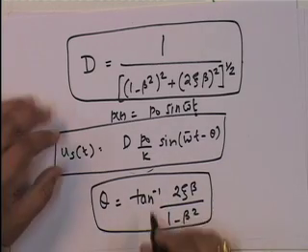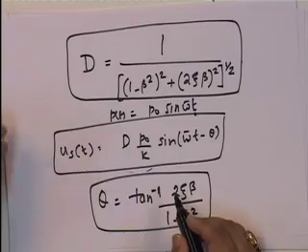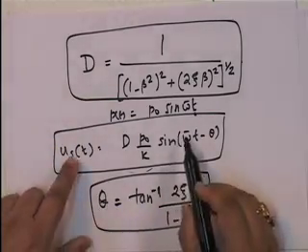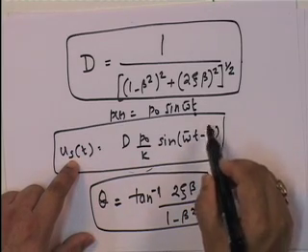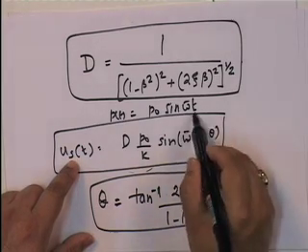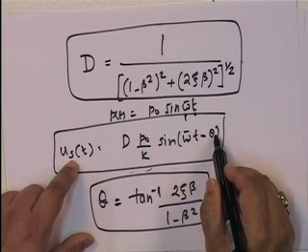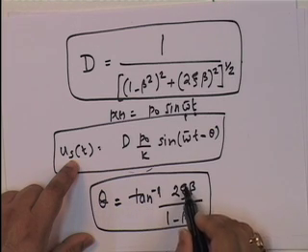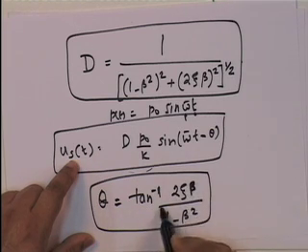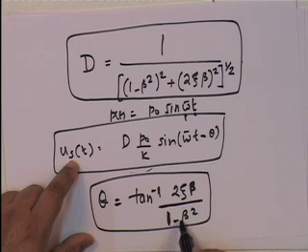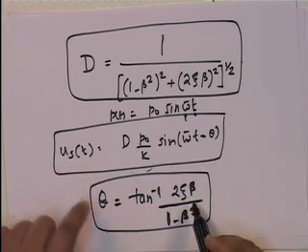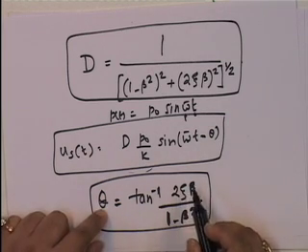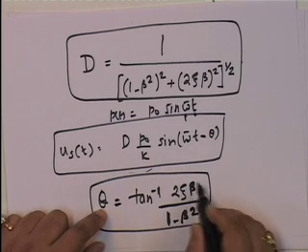You see the beauty of this. So, although we have done a lot of mathematics behind it, the steady state lags the load by an angle theta, which is given by tan inverse of 2 zeta beta upon 1 minus beta squared. Note that this theta, as zeta becomes very small, also becomes extremely small for almost all values of beta.